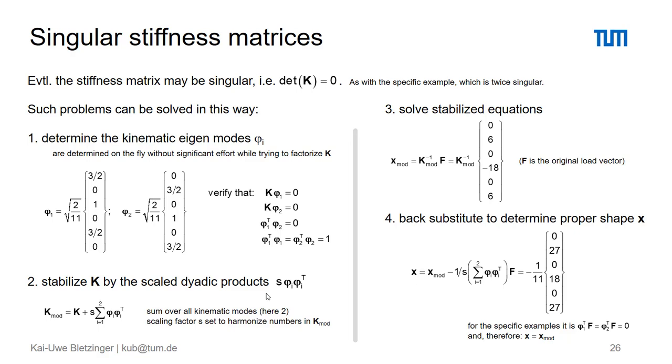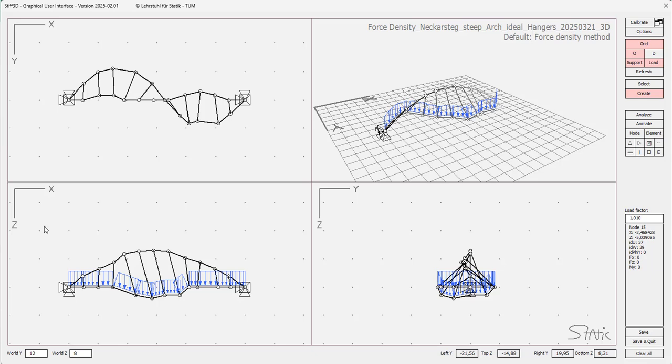The question is, how can we get the eigenvectors? There are quite nice procedures which we can apply by the factorization of the stiffness matrix for our solution, where we still solve for a linear step. That means there is no extra cost at all, or not a significant extra cost, to determine these 0 eigenvectors. Then we can modify this problem we had before here,